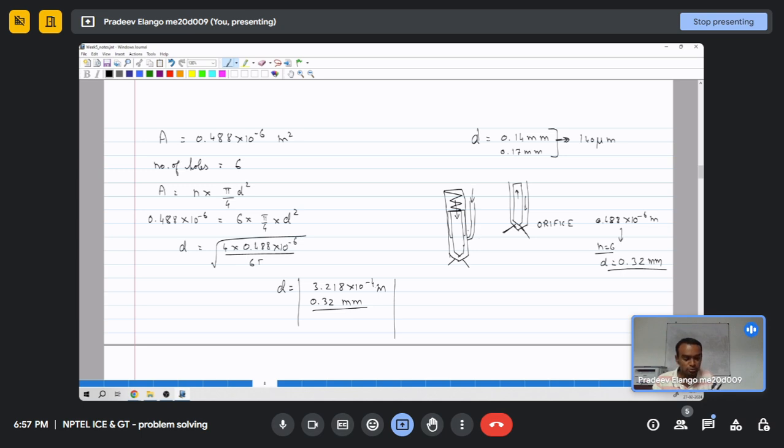And when fuel at high pressure comes to this chamber, because of this change in area, like this diameter will be say some B0, and this diameter on the needle will be B1, which will be a little higher. So that difference in diameter will give an effective area for the fluid pressure, and that will cause an upward force. And when it overcomes the force given by the spring, the needle will start to move upward, and when it moves upward, the hole at this surface will get uncovered, and then this fuel will enter through this and come out of the hole.